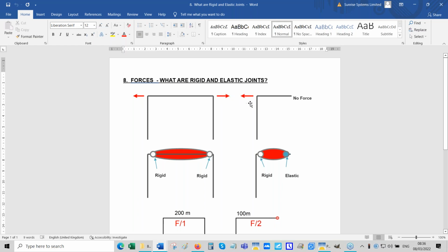People sometimes worry about that, but that's only because PIPENET cannot consider the restraining forces. There'll be other forces which are restraining the pipe from moving. Okay, always keep this in mind. We are only calculating the force that the fluid exerts on the pipe or the piping system.